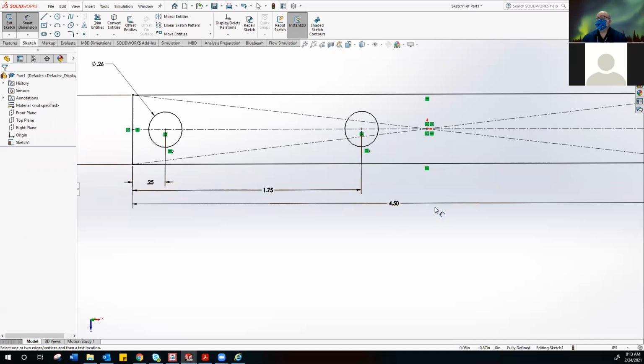That is predominantly the type of dimension you will use in mechanical engineering, because we want one square edge. Because when you're cutting metal or any material for that matter, you want one true edge. And that is your guiding force. We call it a datum point or a reference point. You want material that gives you up to 3 datum points. I mean, most things have 6 sides. So if you can get more points of reference or precision, that makes your product more exacting.